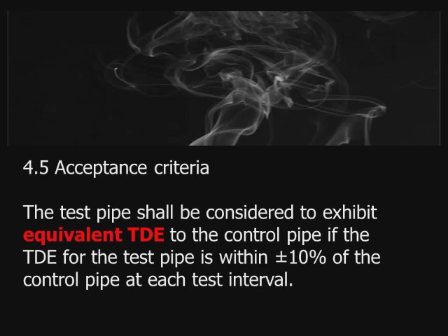What this basically is saying is that when you're blowing hot air through a duct, if it comes out hot, then your thermal distribution efficiency is the same as another duct that is doing the same thing, regardless of insulation. That's pretty much the equivalent of a hair dryer. Because a hair dryer is hot in the back, it shoots out hot air. If this hair dryer were buried or insulated in the ground, it would have the same thermal distribution efficiency as that hair dryer that is not insulated. This really has nothing to do with R value.